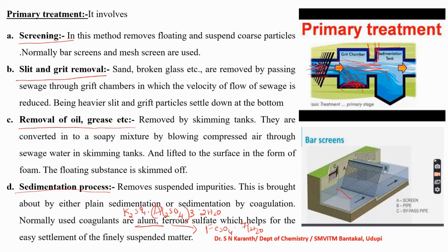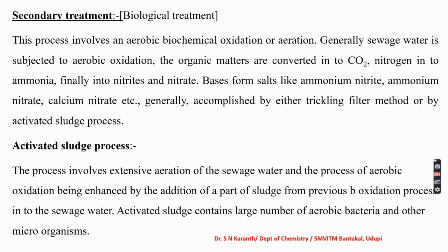These charged particles neutralize the charges present on the colloidal particles, or the spongy voluminous precipitate entraps the colloidal particles and helps in the settling process. Then this water, which is free from suspended or solid floating objects, is subjected to the secondary treatment.